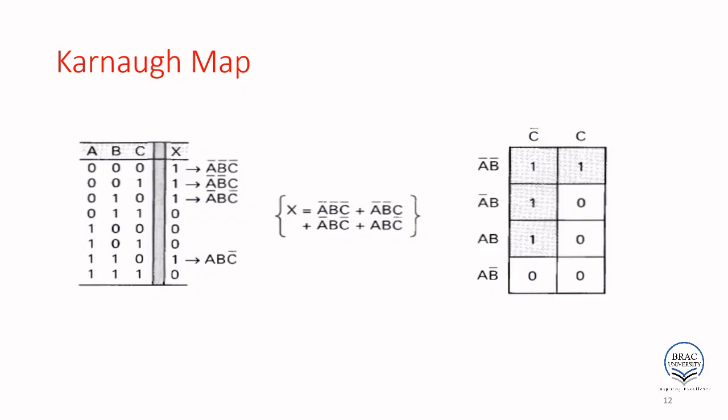So remember, your 1 0 is here, 1 1 is here, because if you look at the 0 and 1 values, only one bit can change in a Karnaugh map. That's why after 0 0, 0 1, then it becomes 1 1 to make the one bit change, then 1 0. So here it is C prime, so it is 0 and 1. So you have 0, 1, 2 and 6 high, the others are low. So this is the representation.